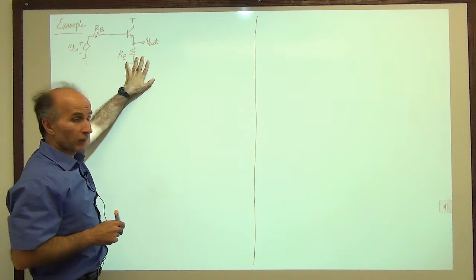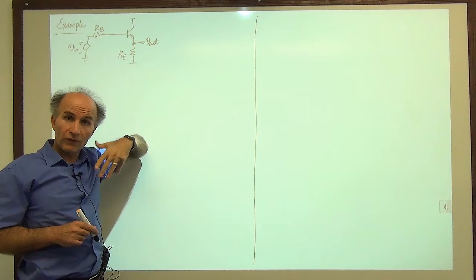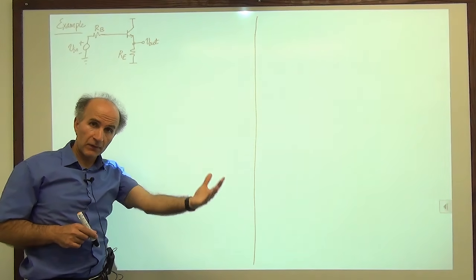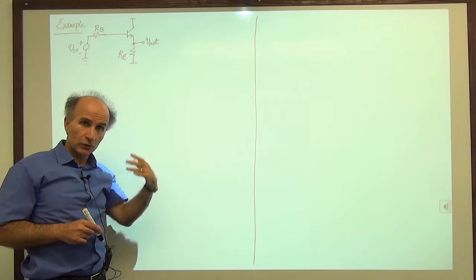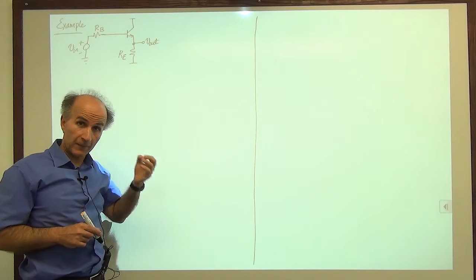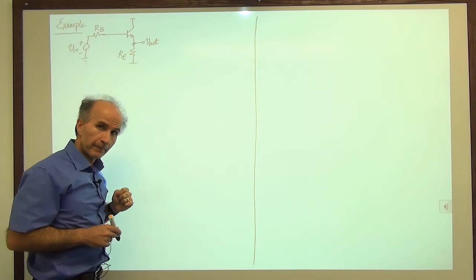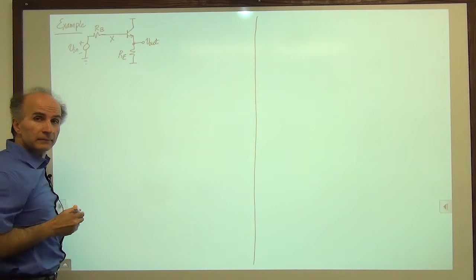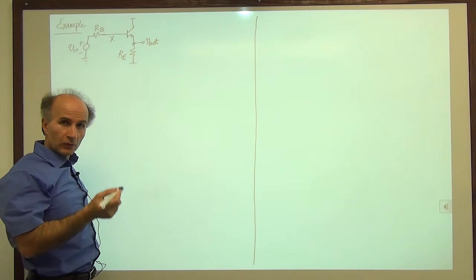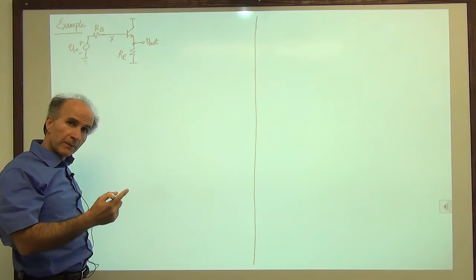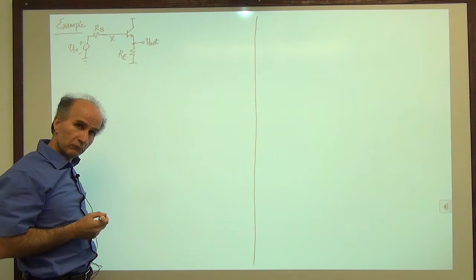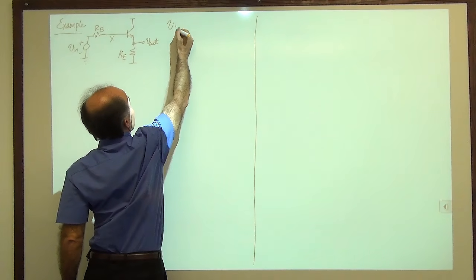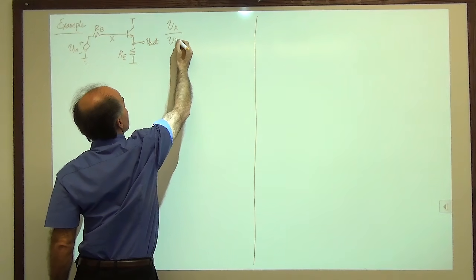Well, you can always draw the equivalent circuit, but again, we want to resist that temptation. We want to look at the circuit for a little while and see if our previous results can be used to find, for example, the gain by inspection. All right, well, why don't I do this? Can I call this node X? And as usual, I say the total gain is Vx over V in times V out over Vx, right? Let's do that. So how much is Vx over V in?